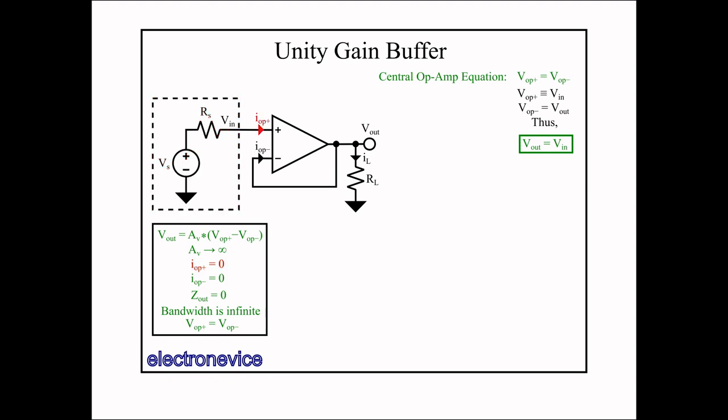This is representative of many kinds of signals, from sensors to simple resistive dividers. Recall that in our ideal op-amp, the input currents are 0, which means the series resistance, Rs, doesn't matter, and that Vin equals Vs regardless of the value of Rs. Additionally, recall that the output impedance of an ideal op-amp is 0, so it can drive a very heavy load, and the output voltage will not change as a result of the load. Thus, the output voltage is unaffected by the value of RL. The input signal alone would not be able to accomplish this, as any current drawn by RL would cause voltage to be dropped across Rs.